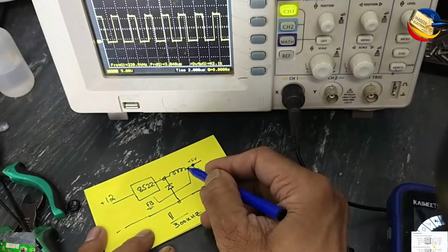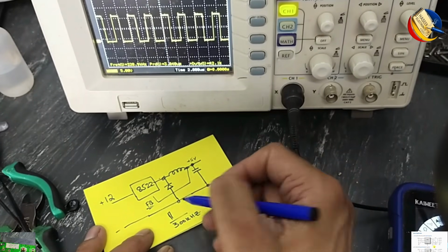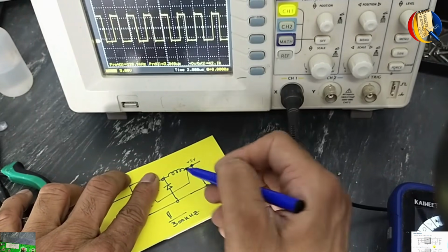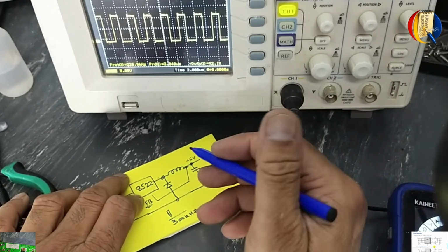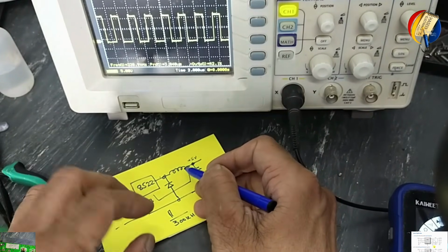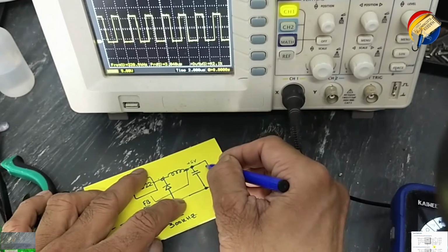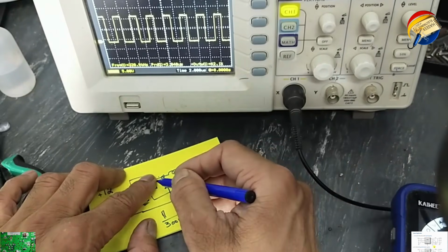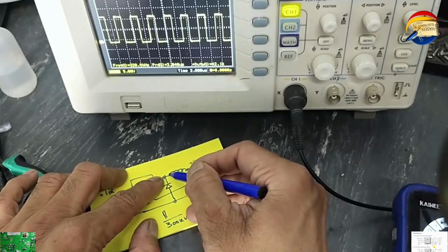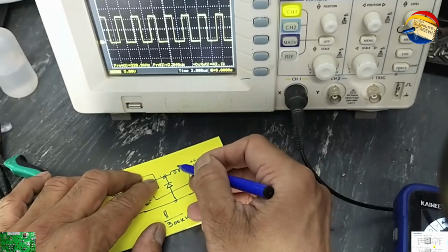When voltage is maintained, it will receive feedback and turn off switching. When switching is stopped, now it is disconnected. Before this, when current was passing, this end was positive, this end was negative. Now when the magnetic field collapses, this end will become negative, this end will become positive, and here is the load resistance. That time this diode will give a discharge path to that stored magnetic field.